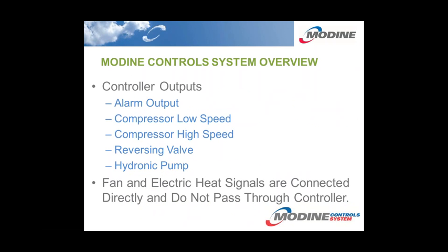Outputs for the controller, we have an alarm output that would go to an L terminal on a conventional thermostat or to an alarm terminal on a water-to-water zone controller or boiler controller. The compressor low and high speed signals are also generated from the controller, as well as the reversing valve and hydronic pump if equipped.